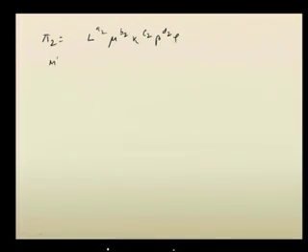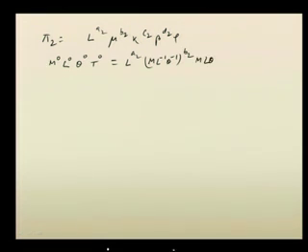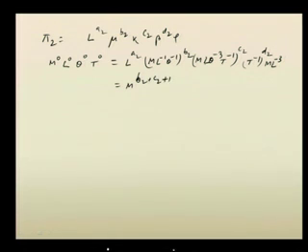So, we will write m to the power 0, L to the power 0, theta to the power 0 and t to the power 0 equals L to the power A 2, then m L to the power minus 1 theta to the power minus 1, whole to the power B 2, then m L theta to the power minus 3 t to the power minus 1, whole to the power C 2, then t to the power minus 1, whole to the power D 2, and then m L to the power minus 3 for rho. So, finally we get m to the power B 2 plus C 2 plus 1, L to the power A 2 minus B 2 plus C 2 minus 3, theta to the power minus B 2 minus 3 C 2, and t to the power minus C 2 minus D 2.